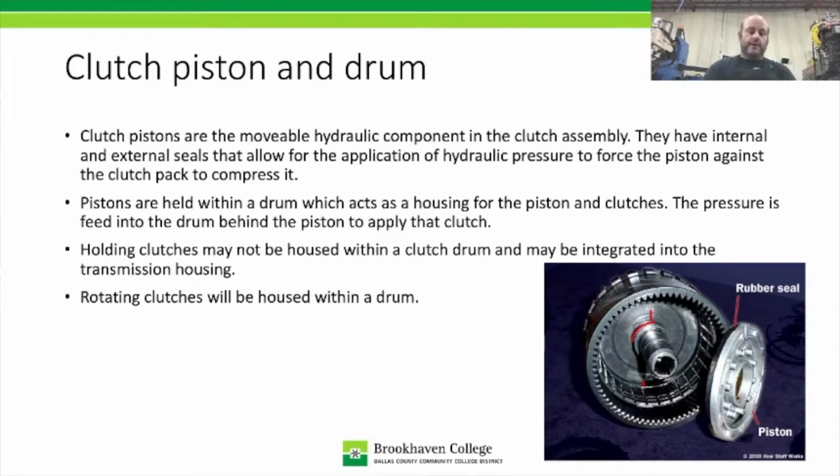Now if it's a holding clutch, the piston doesn't rotate. It's actually located somewhere in the housing or in a support that is bolted or snap ringed into the housing. Those are going to have pistons that are located in that housing or in the transmission case. They're not going to rotate. So the piston's bore where it sits is integrated into the housing or that support housing. And like I said, rotating clutches will be housed within a drum.